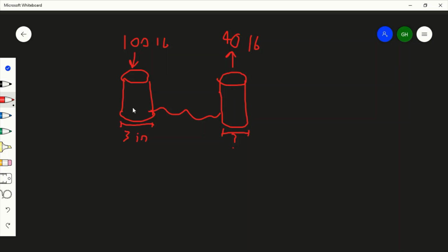So, in order to do that, we can say that the pressure inside of piston A is the same as the pressure inside of piston B. This is going to be piston A, and this is going to be piston B. So we know that the pressures are going to be the same, meaning that we can say 4 times force of A over pi times diameter squared A is equal to the force being applied, in this case still applied, to piston B over the same with diameter squared B. Now 4 and pi can cancel out, thankfully.